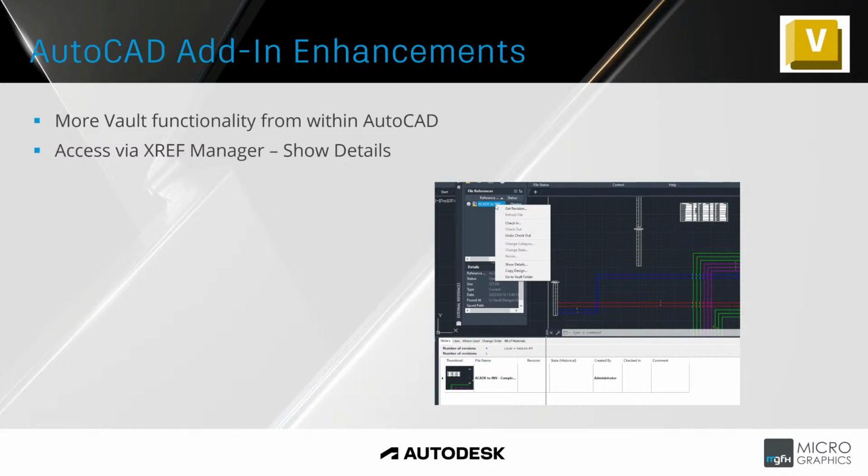Once you've done that, you'll see the drawing, and also any XREFs that are attached to it. So if you've got an AutoCAD drawing and you've put it into the Vault, any XREFs or OLE objects attached to it will all go into the Vault as well. And if you aren't using Vault with AutoCAD, this is actually a great time to think about how many times, if you are working with XREFs or pictures and things like that, you open up a drawing and it's not there. It says, sorry, can't find it, please look for it. With Vault, if you're working with Vault and AutoCAD, that's not going to happen anymore. Vault will take care of all of that, so you do not need to worry about having to look for components, files, or pictures anymore.